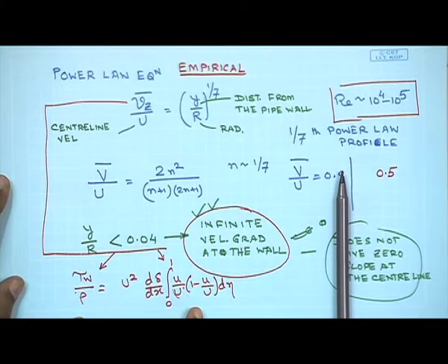If you look at these two sides, it becomes apparent that you may be able to use the 1/7 power law on the right hand side, since you are integrating the expression over the entire flow regime. That is, you are integrating from 0 to 1 over d eta.